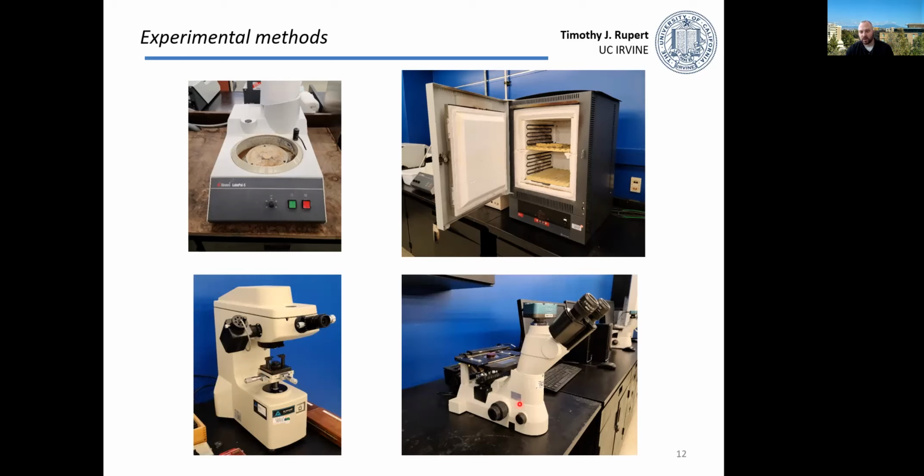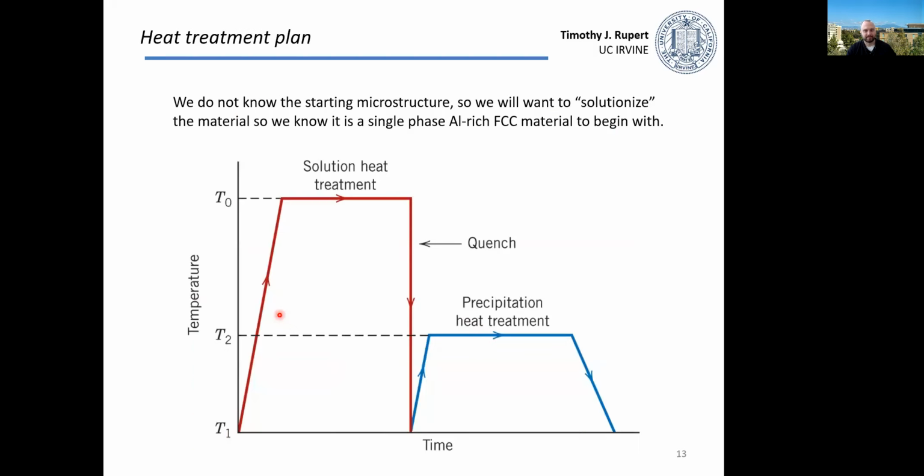Okay, last but not least, we're going to use some optical microscopy. For example, this type of equipment lets me measure those indents as a batch, whereas on the hardness tester I have to measure them one by one, and it gives slightly better images of that. For our remote version, it's also nice because there's a video camera on the microscope. There isn't on the hardness tester.